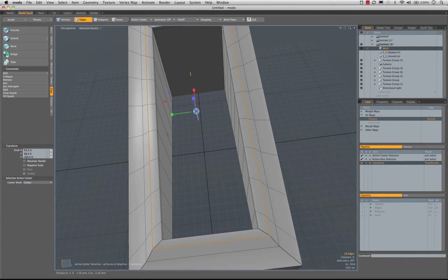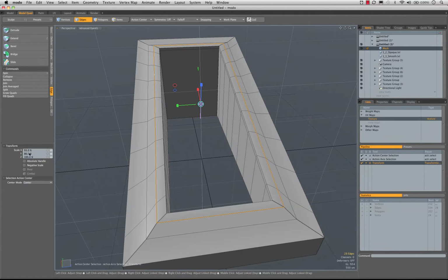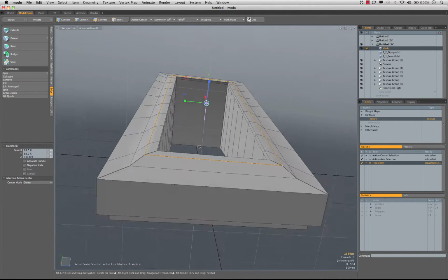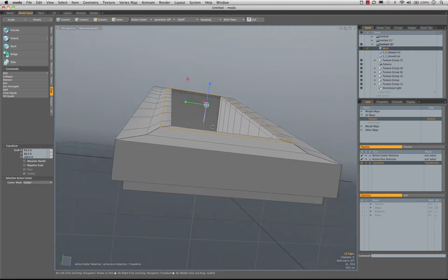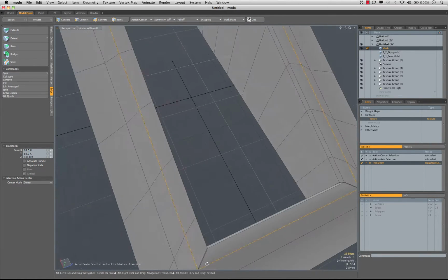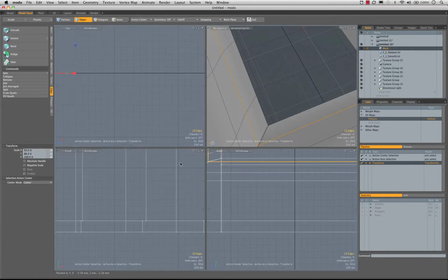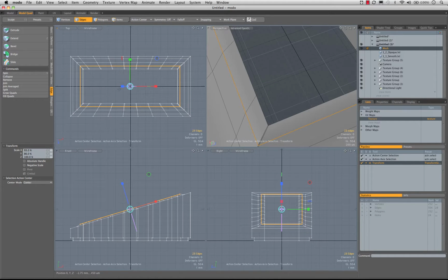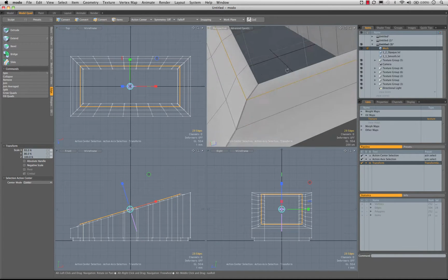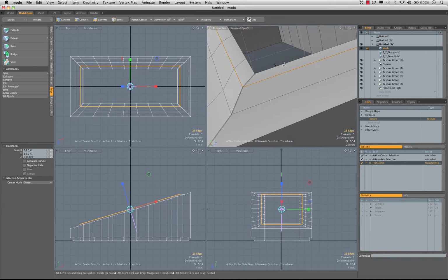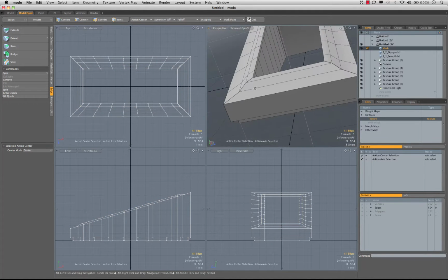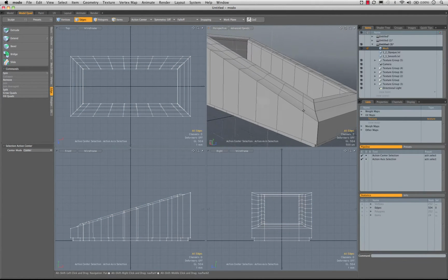And we're nearly 2-to-1, so we should be almost a 2-to-1 ratio on the amount of scaling. So I scaled in 7% on the X. It should be about 14% on the Y. So I'm going to put that value in first here and then go and check. Let's look at that in the ortho. That's actually kind of hard to tell because of the tilt on it. But I think that's looking about right. So we should be good there.